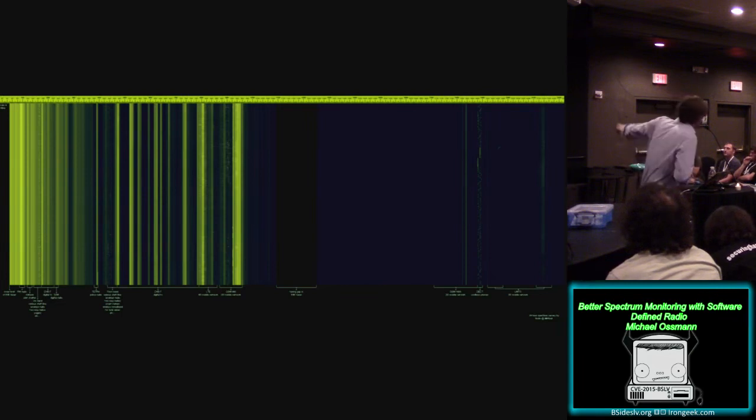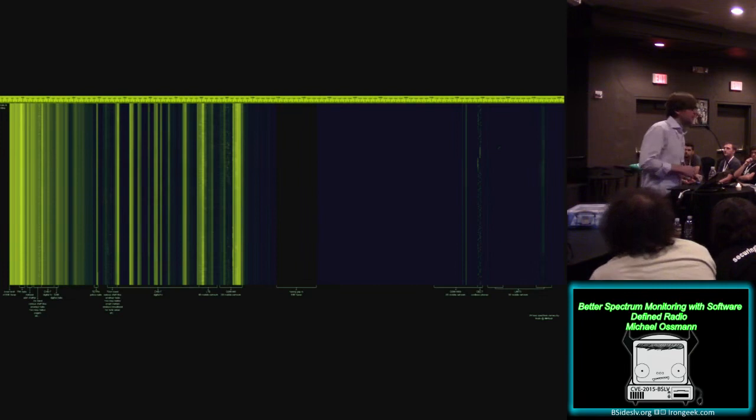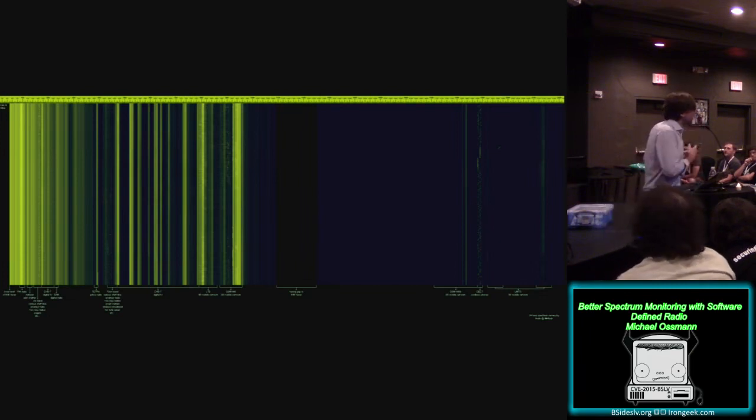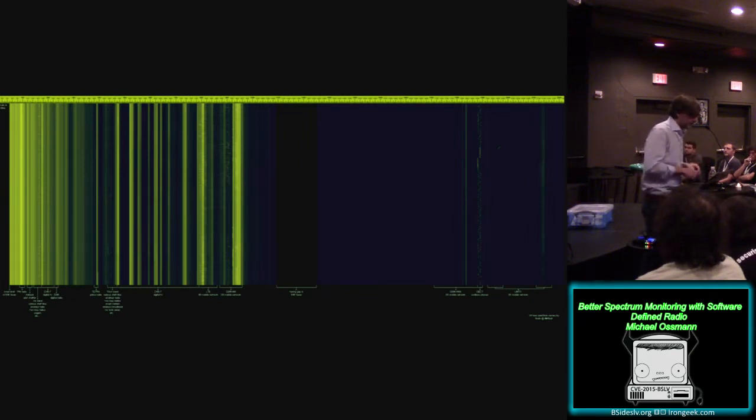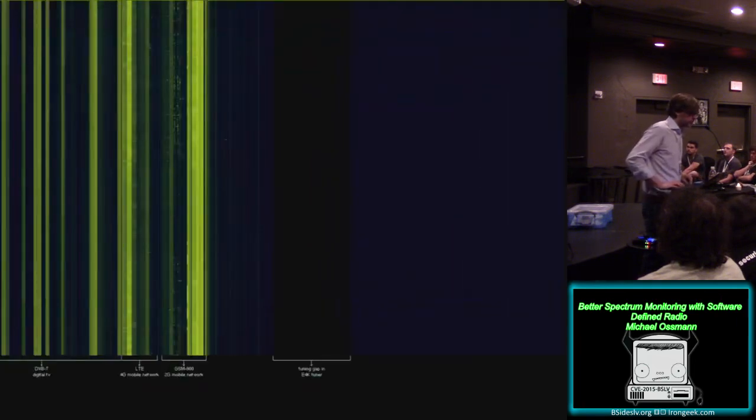There's a little gap in the middle with no information because that particular tuner on the Realtek dongle has a tuning gap and isn't capable of measuring those frequencies. There's a bunch of mobile phone bands. That's most of the bright stuff just to the left of that gap. And you can see some public safety radio systems and amateur radio stuff. All sorts of cool stuff.